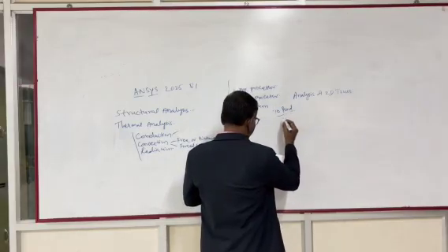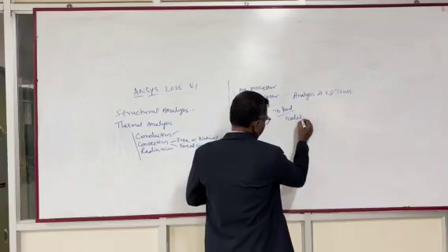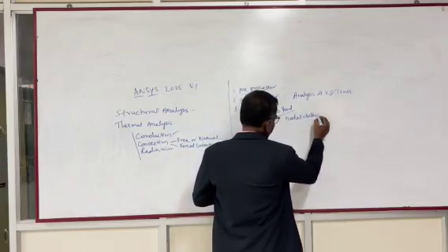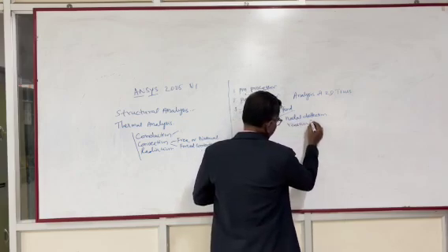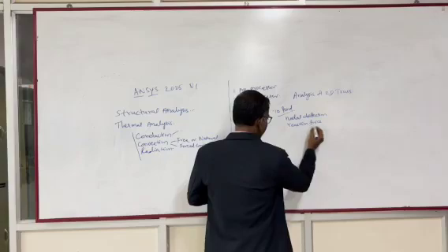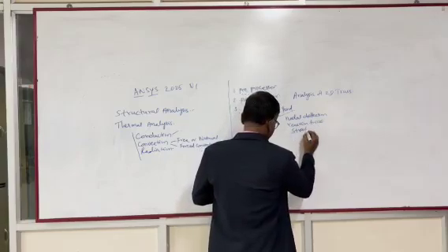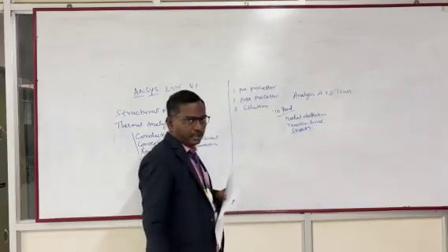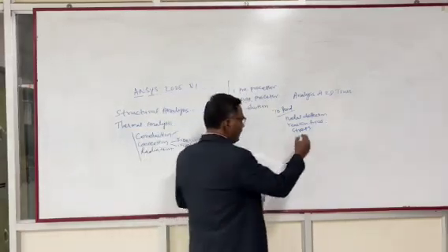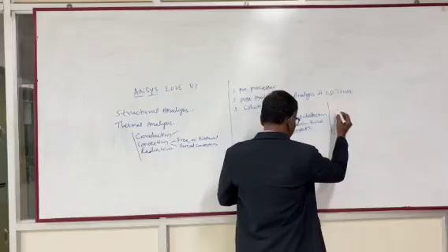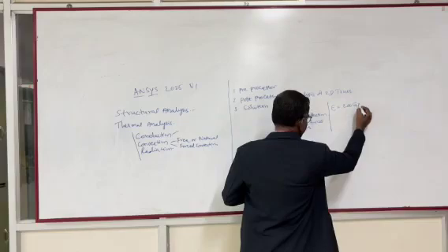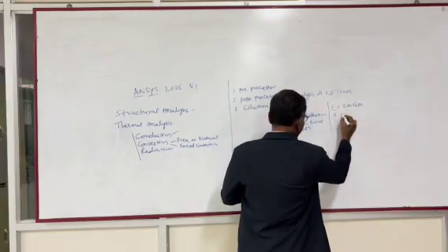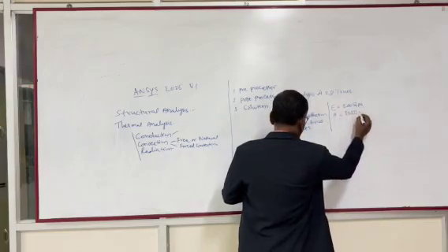So what data do we need to find? Nodal deflection, reaction force, and stress of the system. These are what we are going to find, and the given values for this problem are Young's modulus equal to 200 gigapascal, and the area value given as 3250 mm square.